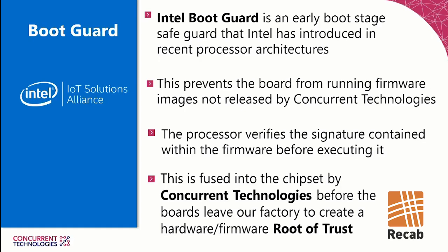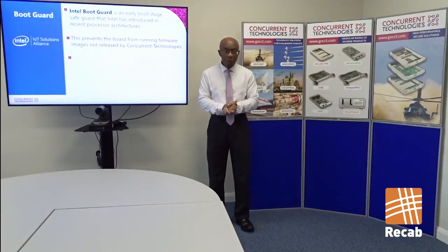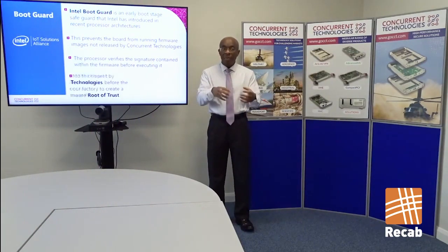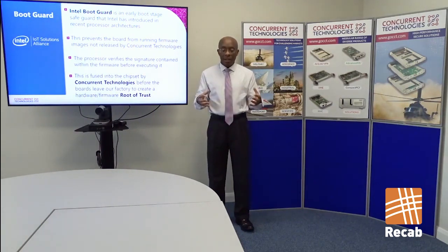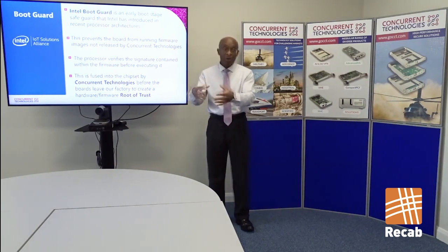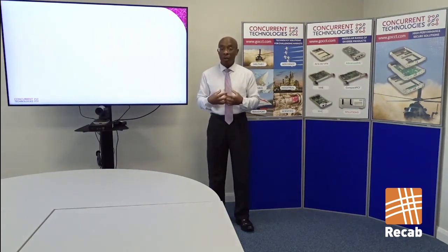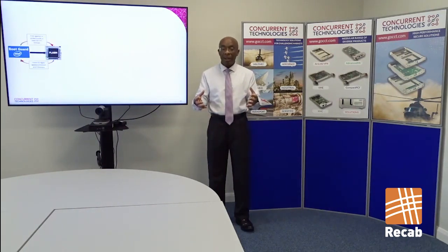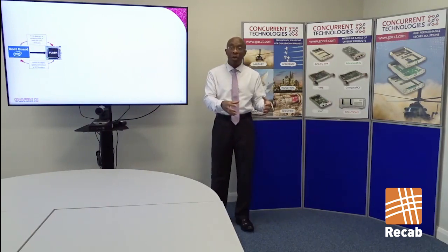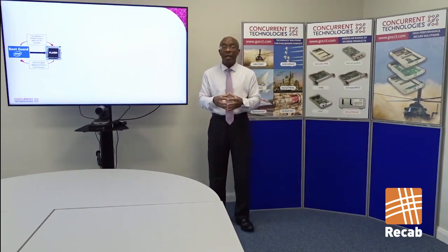So companies like Intel have come up with some technology called BootGuard, where in their hardware, in the chipset itself, there is the ability to fuse information about the certificate signature used to sign the UEFI BIOS. So this is what we do at Concurrent Technology. Before we ship any product, we sign our BIOS, and that gets fused onto the board, such that if anybody tries to install a different BIOS to the one we provide, the machine won't even start.